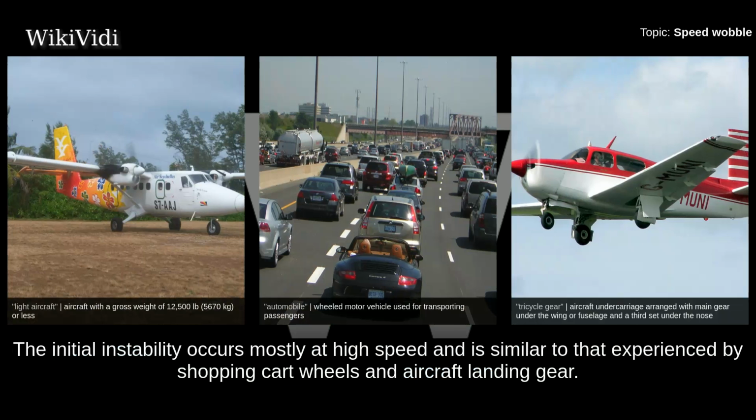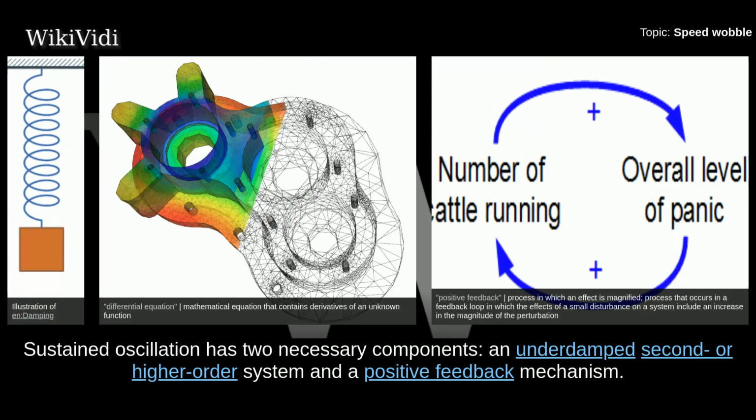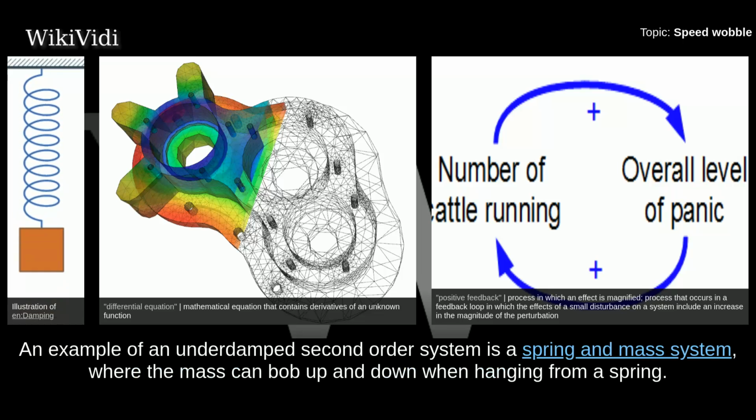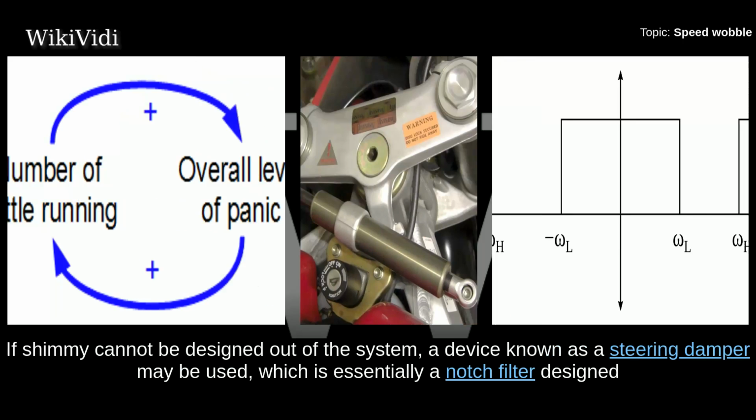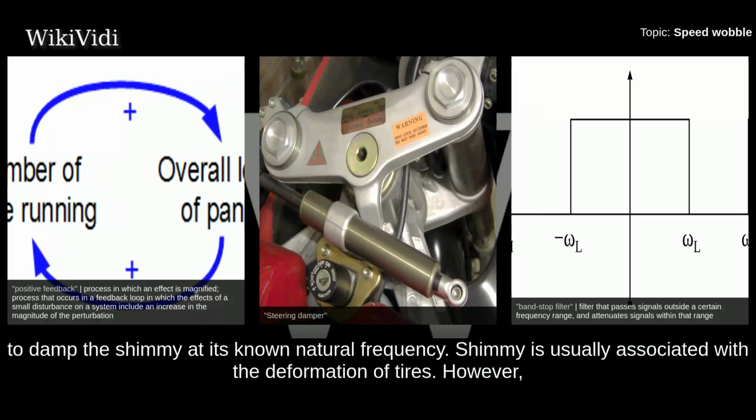Theory. Sustained oscillation has two necessary components, an underdamped second or higher order system and a positive feedback mechanism. An example of an underdamped second-order system is a spring and mass system, where the mass can bob up and down when hanging from a spring. If shimmy cannot be designed out of the system, a device known as a steering damper may be used, which is essentially a notch filter designed to damp the shimmy at its known natural frequency.